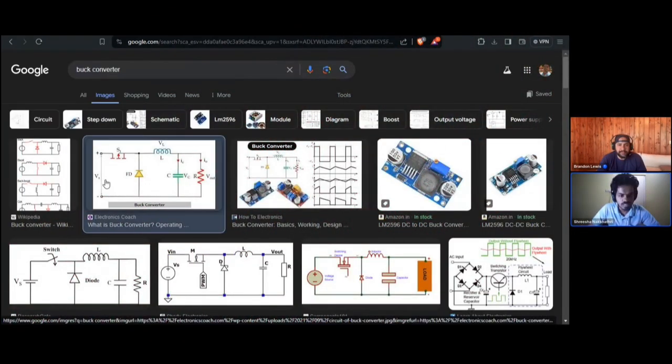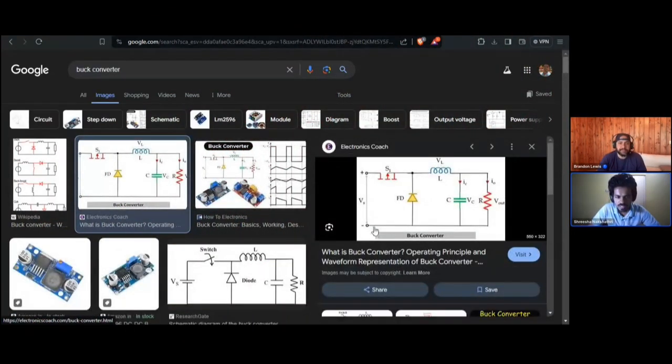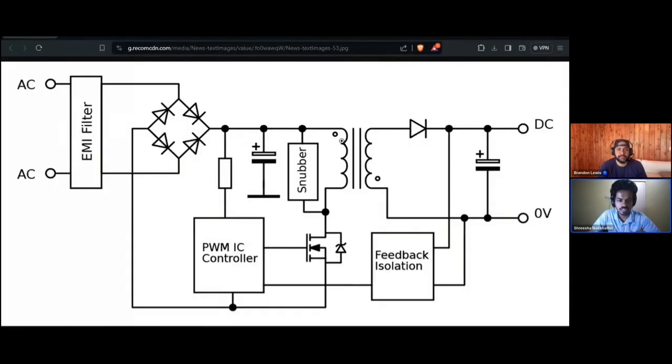This is what it would look like most of the time. If you consider one of these points, there would be much more, like your rectification circuits here. But if you consider this live and neutral, one of your lines is directly connected to your output, and the other line is directly connected too. So it's not completely isolated from the supply. In the isolated case, this entire circuit is completely isolated from this entire circuit. Here your feedback would be there, but the feedback is also completely isolated. It would be something like optocouplers, otherwise it would be a transformer winding itself.